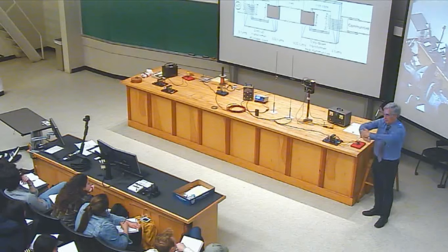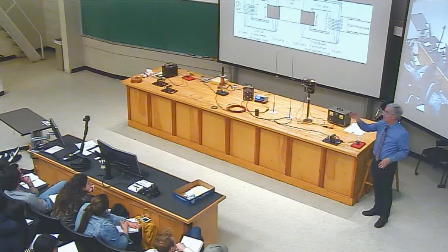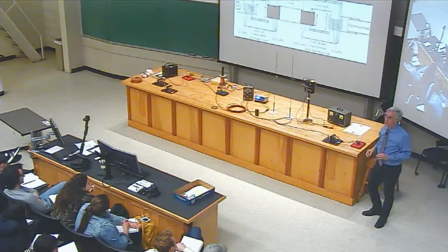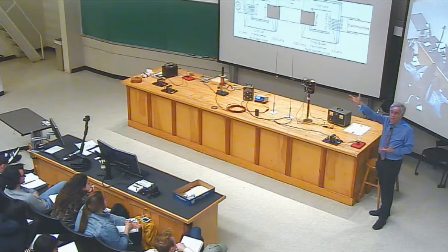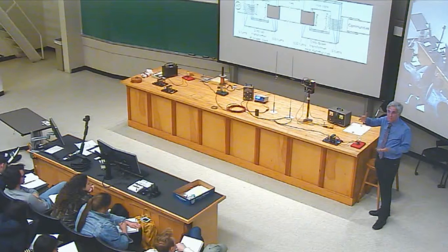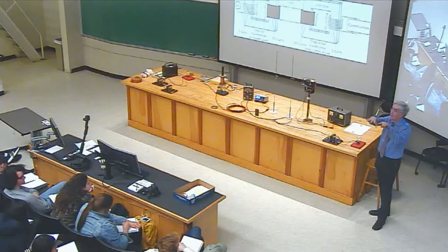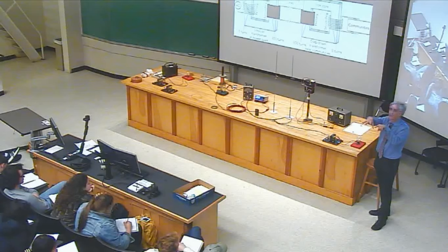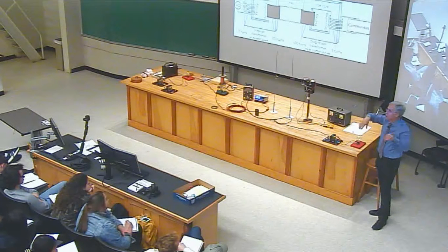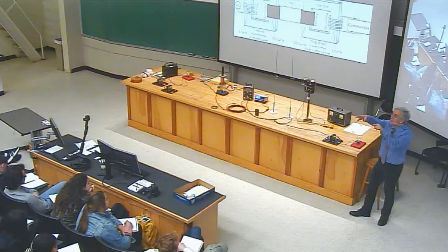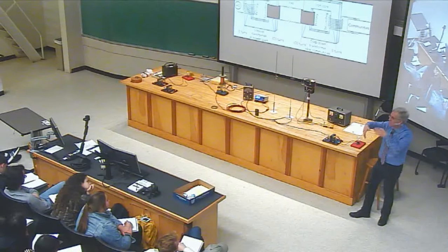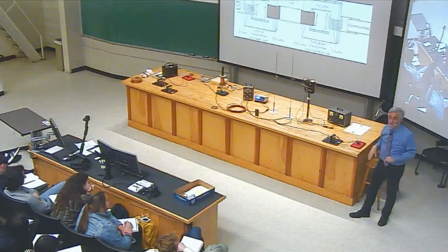They're about this big around, about that tall. You'll see the thin wire come in. That's going to be the part of the high voltage circuit. And then you'll see one or more, a couple of wires coming out of the transformer that are much thicker and typically insulated at this point. The wires going in, the high voltage wires, have no insulation. They're just open, bare metal. The power coming out, much thicker wires and much lower voltage.